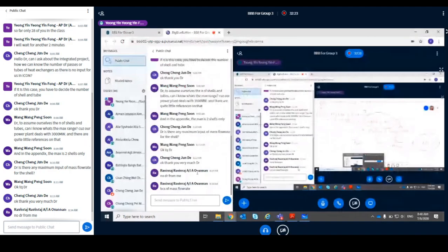Okay. The determination of Qmax requires the inlet temperatures of the hot and cold fluids and their mass flow rates. Once the effectiveness of the heat exchanger is known, the actual heat transfer rate can be determined from this equation. You just rearrange the equation, then you will get the Q. In fact, if you know the inlet and outlet temperatures, then you can get the effectiveness.